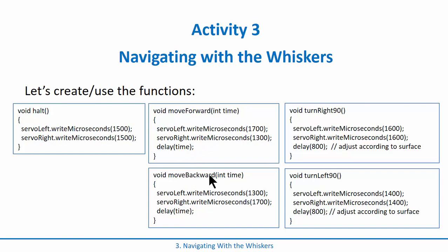Exact same situation when I do move backwards, except that I'm going to just reverse the motors, so it's 1300 on the left, 1700 on the right, and then I'll delay again. And this is going to save me a little bit of effort when I'm programming.